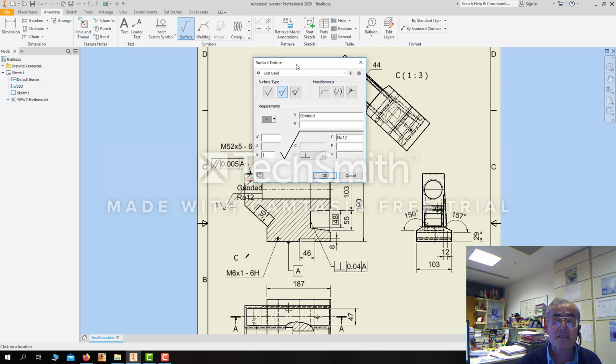Now in this dialog box, the boxes ready to accept the things to write into the boxes and also their places are all in accordance with the format of the old version of the standard. Well, in the old version of the standard, ISO says that this is the box to write the roughness value. If it is arithmetical average roughness, then the Ra abbreviation is to precede. Okay.